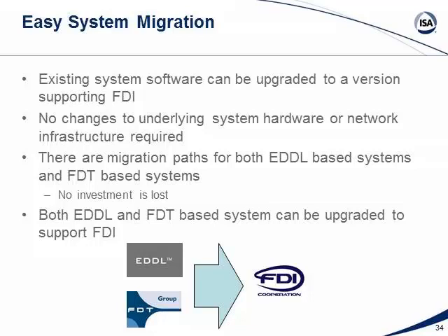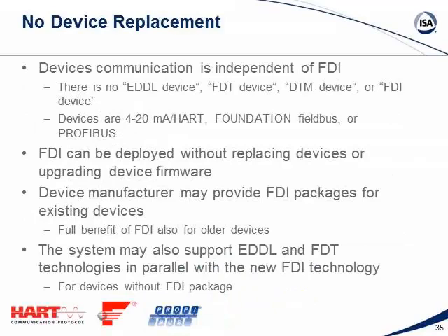And again, we're talking driver files here. We're not talking about device firmware. I can speak certainly with authority on Foundation Fieldbus. There's not a single thing in FDI that requires any change in firmware to those existing devices. Now, certainly if I was building a device from scratch, I might think about some things to make it easier. But the nice thing is FDI can apply to every single device ever registered from the Fieldbus Foundation, back since 1998 when we did our first device.